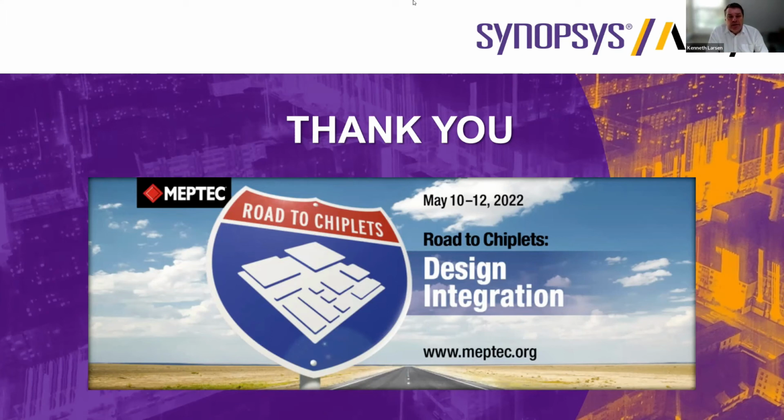There's a big loss if you have multiple dies. You try to integrate this, but splitting the dies up and having them next to each other, you probably use more energy than you really want to. So stacking offers some new attractive ways of reducing and becoming more power efficient. You remove a set of layers of IOs, for example, that can have a significant improvement in power efficiency. We're talking significant improvements. So I think you will see it coming.